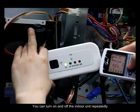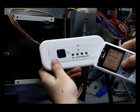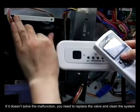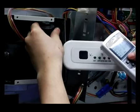You can turn the indoor unit on and off repeatedly and feel the action of the throttle part and the refrigerant flow by hand. If it doesn't solve the malfunction, you need to replace the valve and clean the system.